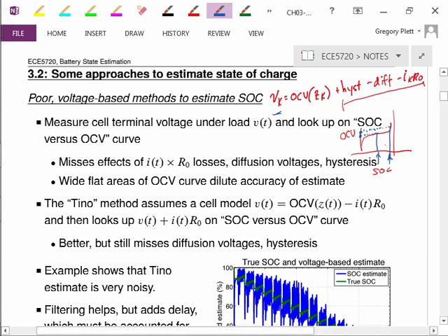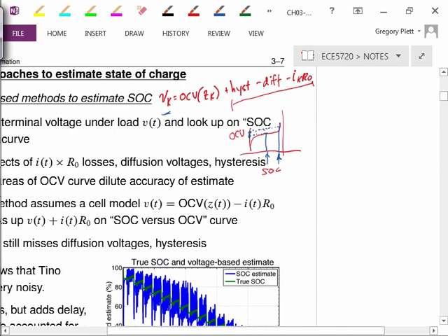Very, very simple. Now, this curve, the OCV relationship, could be stored in a table. It could be a function. Usually what we would do, in fact, is draw the curve the other way, which looks like this. And this is OCV in, and this is SOC out. I just switched the axes. And so if I measure a certain voltage, that allows me to directly compute from it what the state of charge must be. So, very simple. Doesn't work.